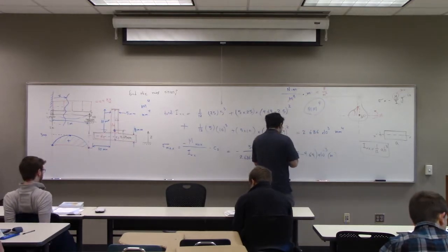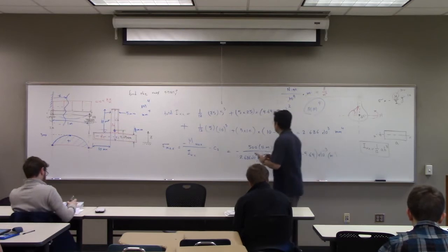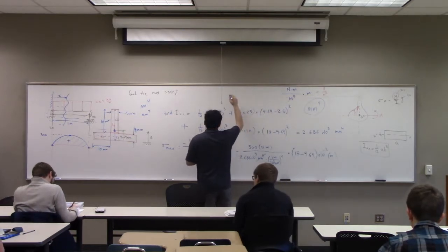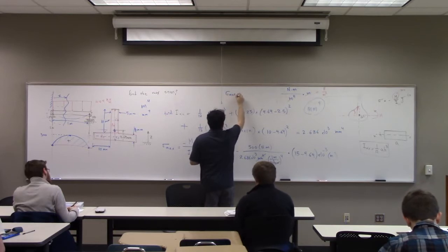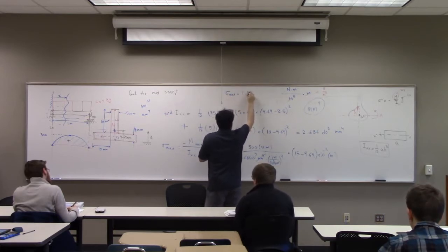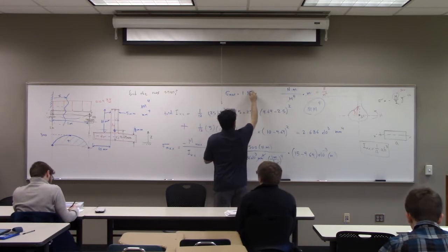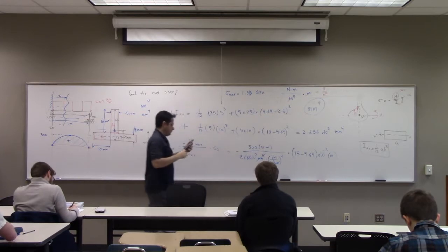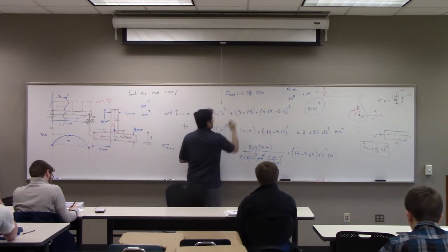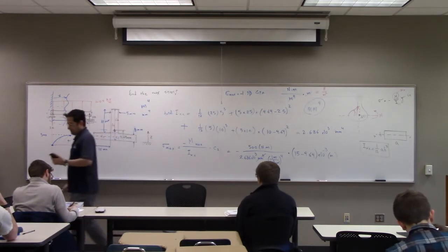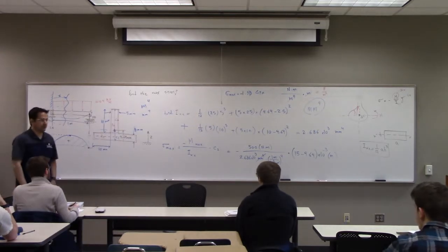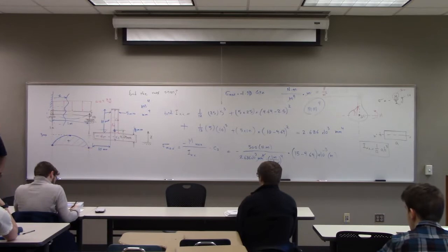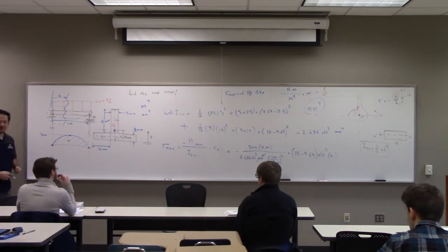So I get sigma max 1.9293 GPa. Too big. Negative. Did you get the same value? Just too big. So if you want to say, well, I want to design, and this is my preliminary design, then you immediately say, go and revise. This is not going to hold.